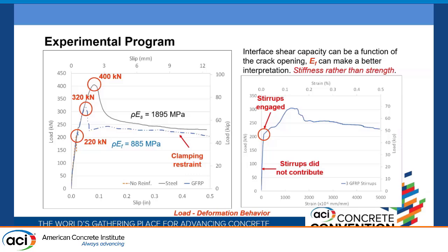Since you have increased the amount of reinforcement, you have already increased the stiffness, and the picture I see is more like you're transferring the shear into a bond failure, because now we're seeing a slippage issue, where the bond strength of the bars counts. And again, everything related to GFRP comes back to modulus of elasticity.